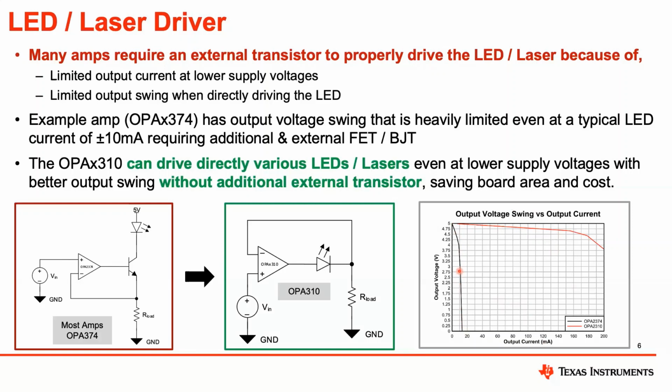So while this unit that I tested here might be able to directly drive an LED, and emphasis on might, because the voltage drop of those LED diodes can vary depending on which one you're using. The real problem is this doesn't take into account temperature variations as well as process variations.